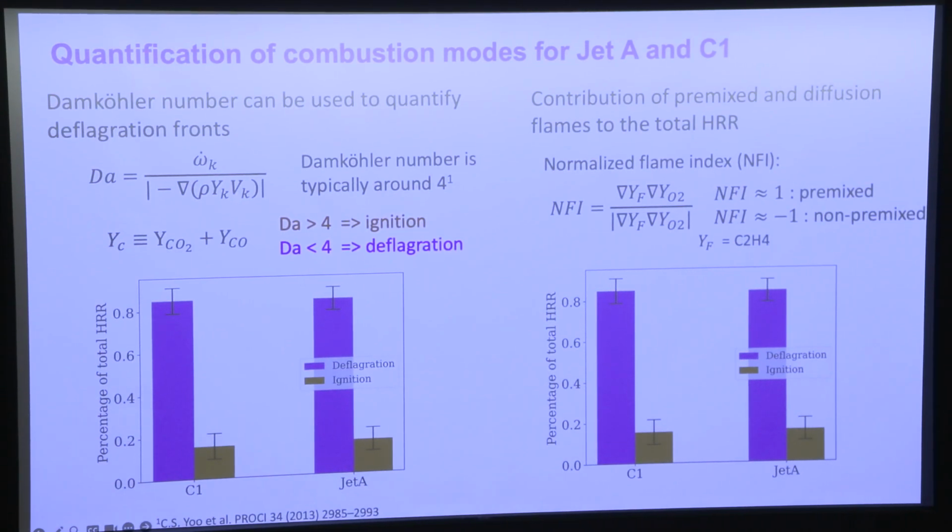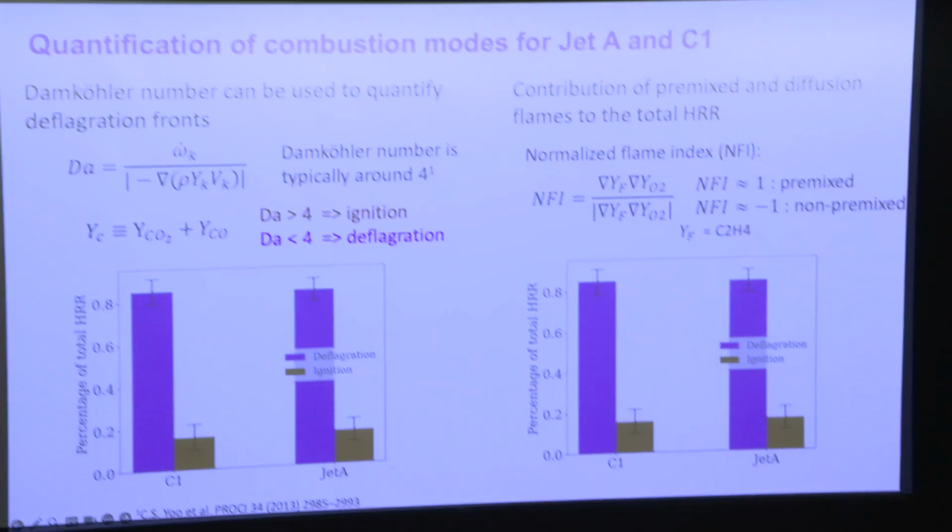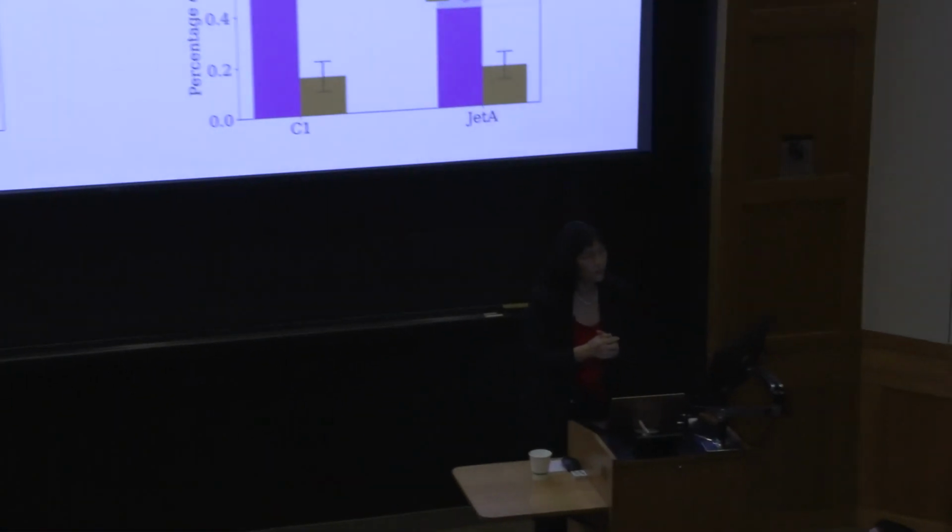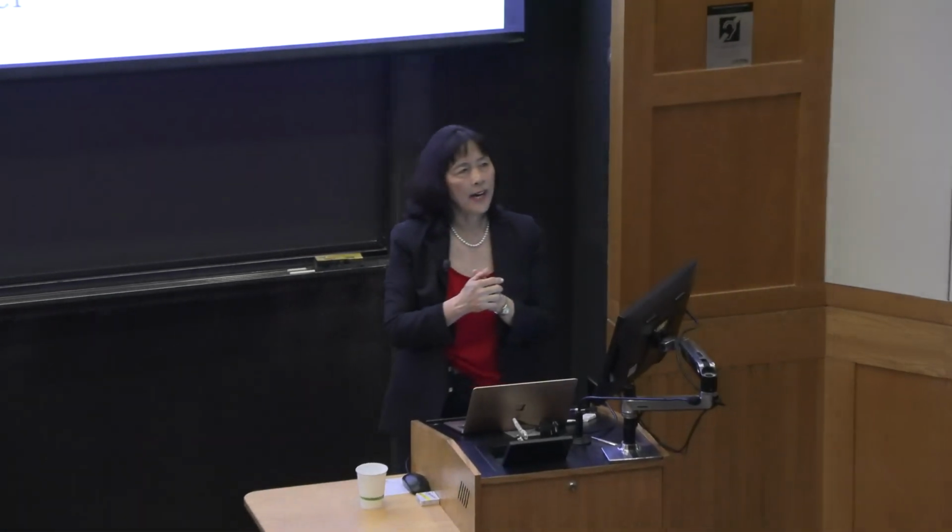it's non-premixed. And I should say these jet fuels are really complicated because when it encounters hot product gases that are a little bit over 1,000 degrees Kelvin, as it does in the central recirculation zone, it pyrolyzes. And so the flames that we see that are running around and getting quenched and reigniting is usually not the original fuel.